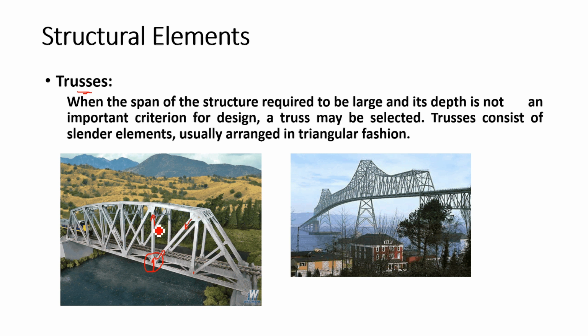You know what the meaning of axial load is? That means the load acts along the axis of the member. So in this case, you will get tension or compression always. You don't get any other forces. There are other types of forces, which I will explain when it comes to forces. So this is what we call a truss, right?